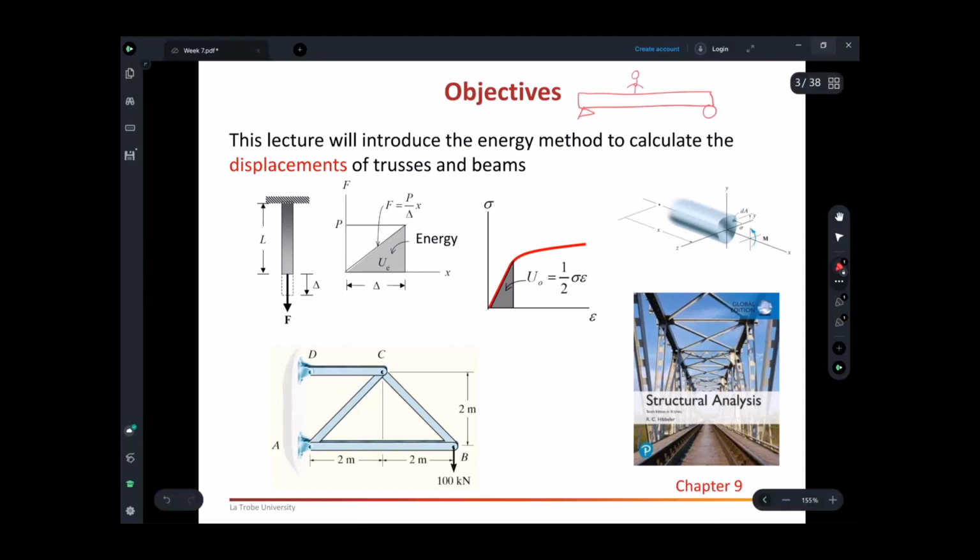So this beam under the load will deflect by some amount, right? But this deflection is not going to tell you that the beam is going to fail or not going to fail. You can't tell from this quantity that if the deflection is too much, it means the beam has failed. There are no rules in structure design and structure analysis saying that by looking at the deflection, you can say that the beam has failed or not failed. Yes, bending moment and shear force can be used to check whether the beam is safe or not safe. But for deflections, this is not the case.